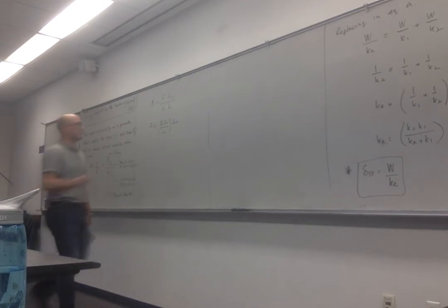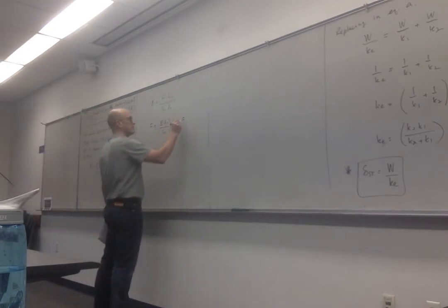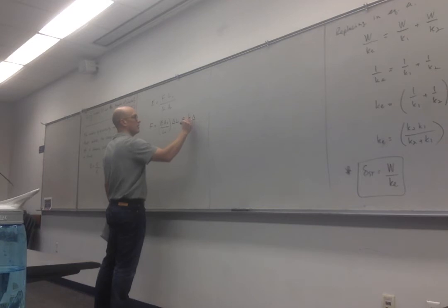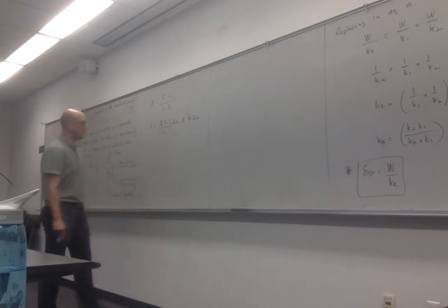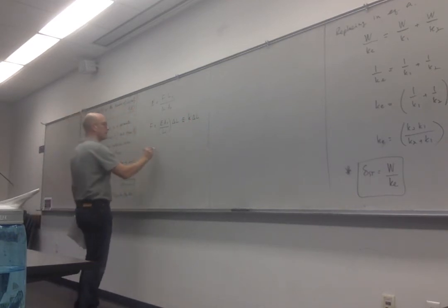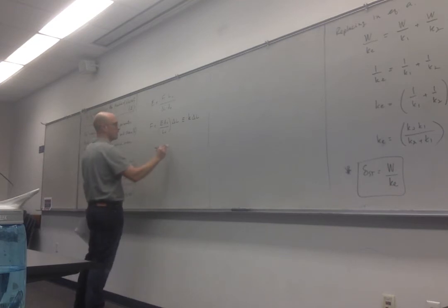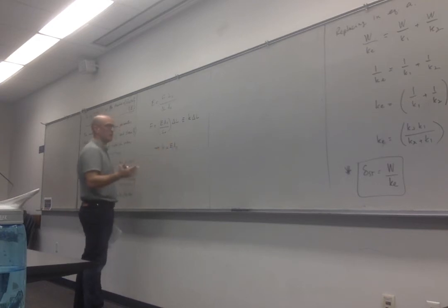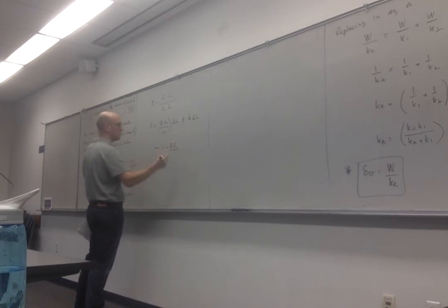If you see this, you should find that this equation is equivalent to K delta L. So in a way, the spring constant of a cushion is going to be given by its modulus of elasticity, the area that is used to bear the force or the weight, and its initial thickness.